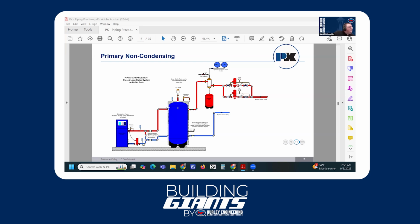And then we can use these tanks oftentimes, like you'll see, as hydraulic separators. So we'll have one loop here and one loop here, and their flow does not influence the other. Even though this is a primary only, we're using it like a primary-secondary with this buffer tank being a hydraulic separator. Thanks for pointing that out, Daryl, because yeah, it's misleading. It is truly a primary-secondary with that four-ported buffer tank.